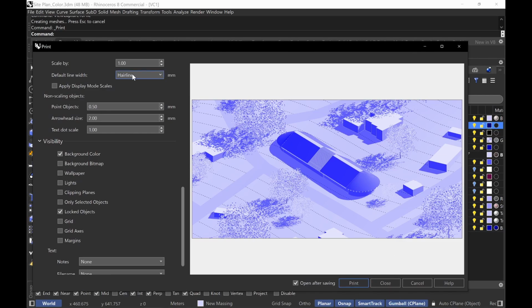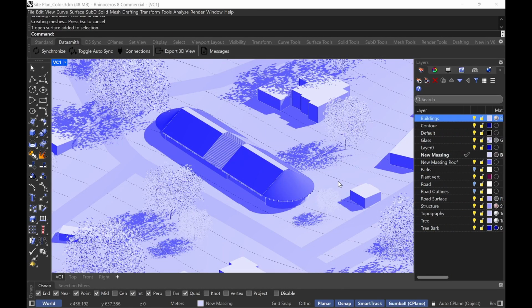The difference between printing and view capture to file is that printing takes a little bit longer to generate, but it's a little bit higher quality. Whereas view capture to file is quicker to generate, but a little bit less quality, but the difference isn't that much. I personally like to just do view capture to file for the majority of my drawings, except for things that have dimension strings on them.